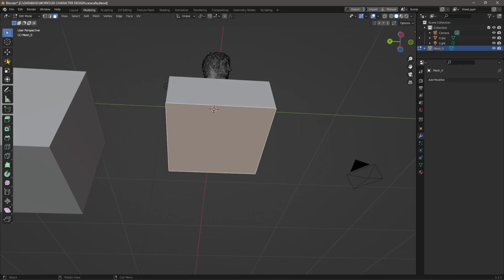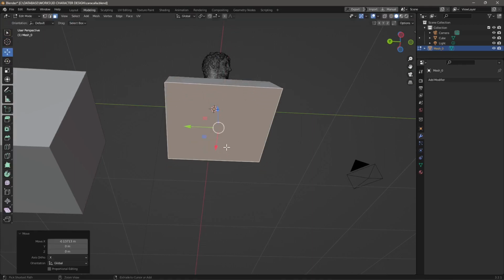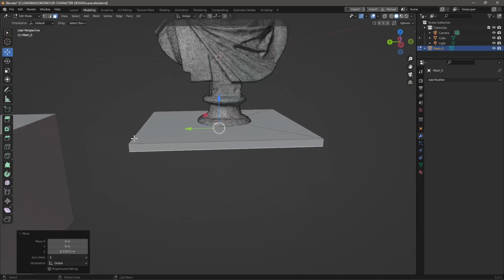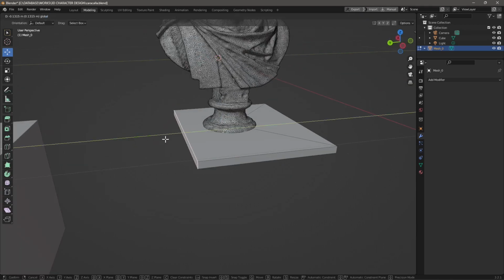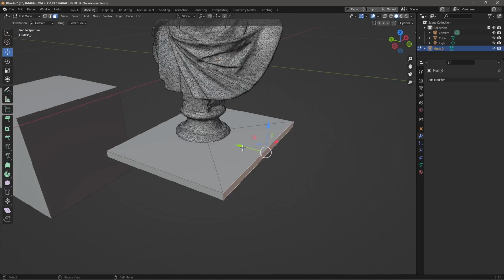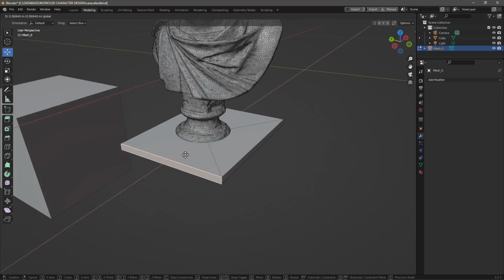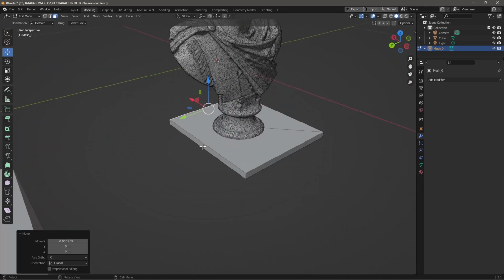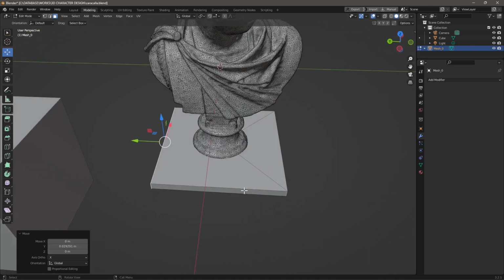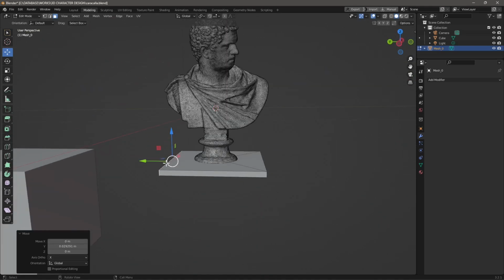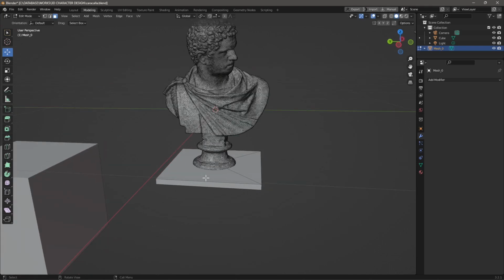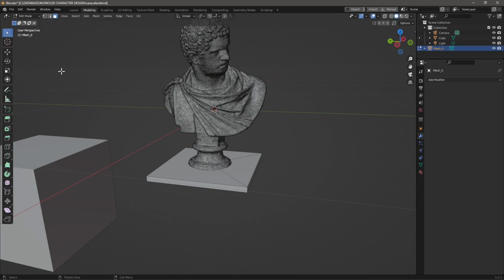And now you can see that I can manage or edit the different faces of these. I can make it smaller, bigger, thicker, thinner, whatever I need, whatever I want. So I can just edit this, continue to edit. But most important, I don't have gaps. I don't have holes. So I can try to send this to 3D printer software and it's going to give me fewer issues, certainly. So this is a way you can prepare for 3D printing and how you can manage your 3D models coming from photogrammetry here in Blender and then move on to 3D printing and other operations.